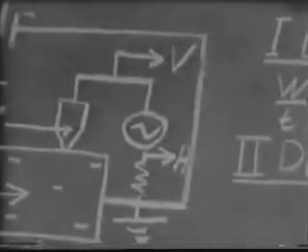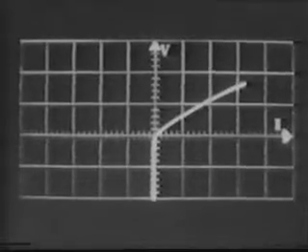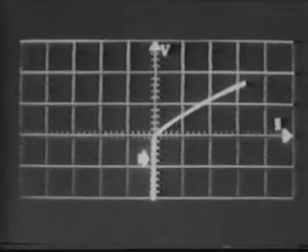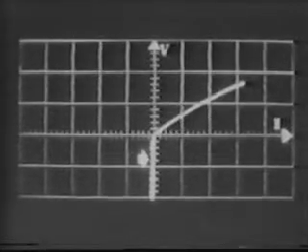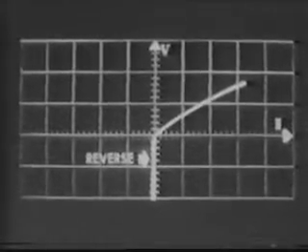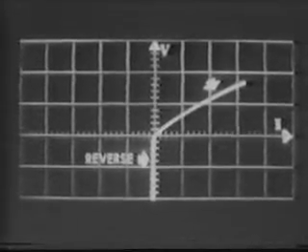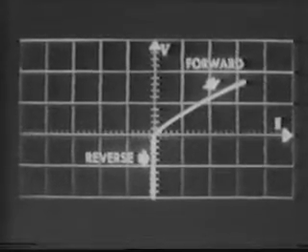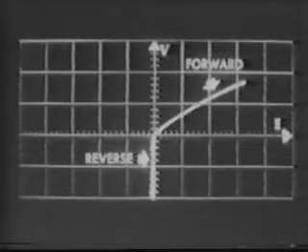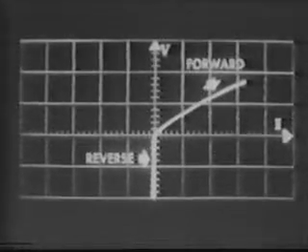The voltage current characteristic on the scope shows that for negative voltages, the current is barely perceptible. This negative polarity, corresponding to difficult current flow, is called the reverse direction or reverse polarity. Positive voltage on the point produces relatively large currents and is called the easy flow or forward direction. This rectifying voltage current characteristic comes from the detector point and not from the low resistance end contact.